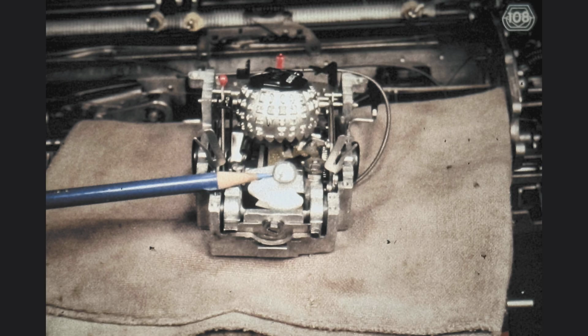Once you have disassembled your carrier to this point, take time out to examine it very carefully to see just how many, or how few, parts are left on that rocker. Actually, it should become apparent now that the system is not very complex at all, and the concept of the universal type bar performing all the printing on the IBM Selectric Typewriter should now be clear to you.